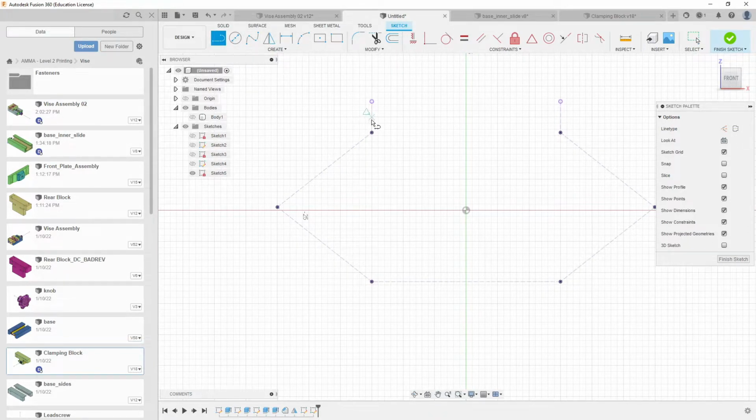So I pick a line, and right now, don't snap it to that midpoint right there. It's going to seem like a good thing to do, but don't. So purposely move it off of it. If I hold down Control, it won't snap, but it won't snap to the line either. So I'm just going to grab somewhere kind of small, low down here. Now I am going to hold down Control because I don't want any automatic constraint being made if I happen to line up with something.